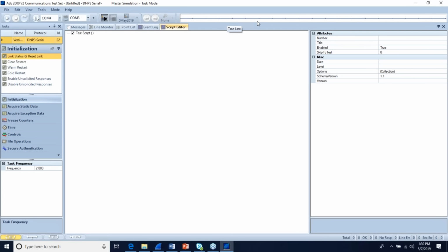And then up on the upper right-hand side, this is our timeline, which is used for real-time display of communication signals. Like the BCOM unit, this is a device troubleshooting aid or an application troubleshooting aid. You'll see live traffic here shortly. It simply will tell you when you see a carrier signal detected and a RTU response. It's a fairly good indicator of when you're trying to identify setup discrepancies or understand why a device is either not responding or you're getting some sort of error result.